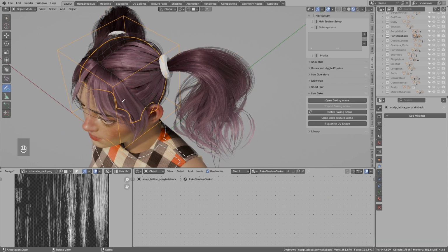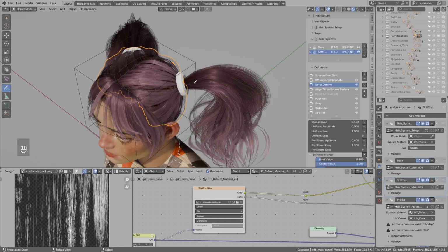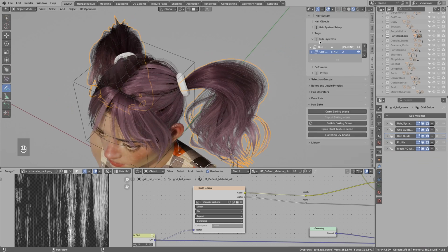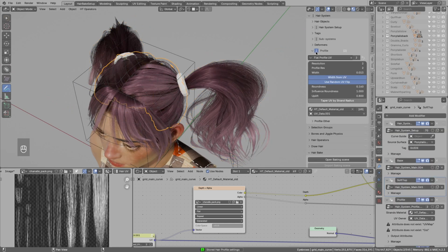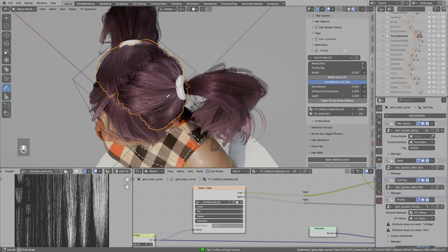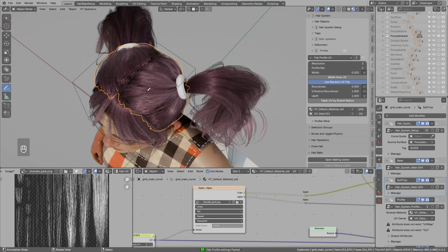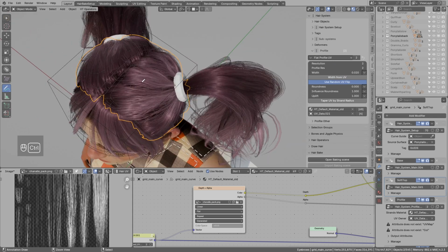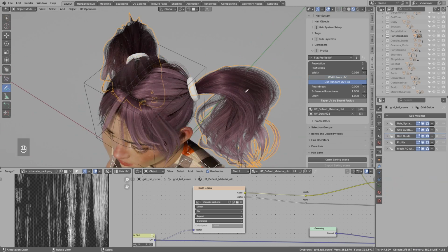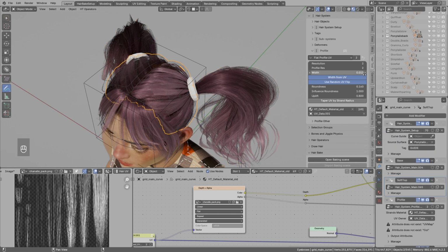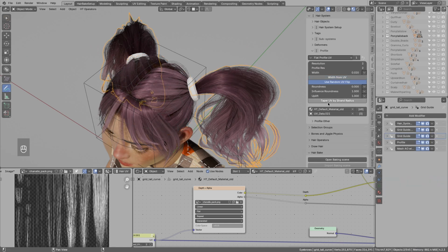And we would have to repeat this everywhere. I could try to, for example, save time by copying the profile and pasting the profile, but it looks like the settings are slightly different, so it does not look exactly the same as the previous layout. Because you see we have width 002 and here 0013, so it is using slightly different settings. So that's why we may need to manually copy UVs.